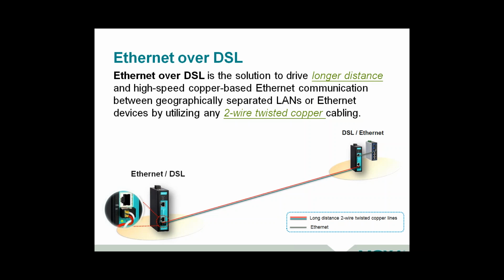So when we talk about Ethernet over DSL, what we're talking about is basically being able to take Ethernet, which has a different physical wire format, and extend that technology over twisted pair copper cabling, which is fundamentally different. One of the things that some of you may know is that Ethernet is full duplex using 2 transmit wires and 2 receive wires. A lot of the magic in this DSL technology is how to multiplex that onto the same pair or 2 pair of wires so that you can both send and receive on the same 2 pair of wires at the same time.